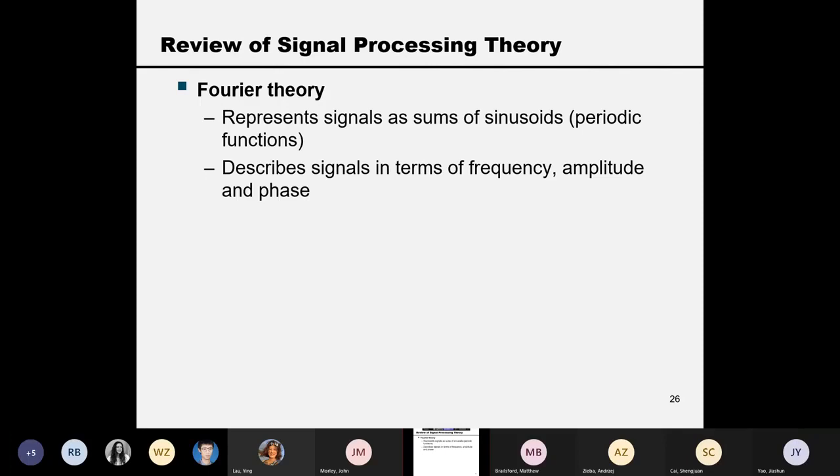Each of those cosine or sine functions has special properties, because cosine or sine are periodic. So they have a fixed frequency. Frequency means how many cycles per time unit, in this case how many cycles per second. They have a special physical unit called hertz, which is 1/second. So we have a constant frequency for the cosine or sine wave, a constant amplitude for each individual cosine or sine wave, and a constant phase. We're talking about detail. What is phase? Phase really means time delay.